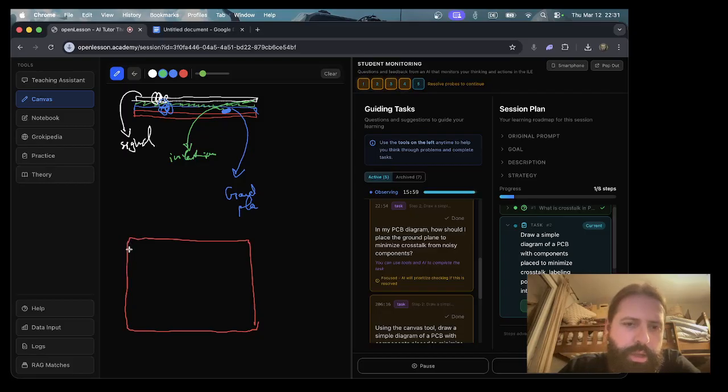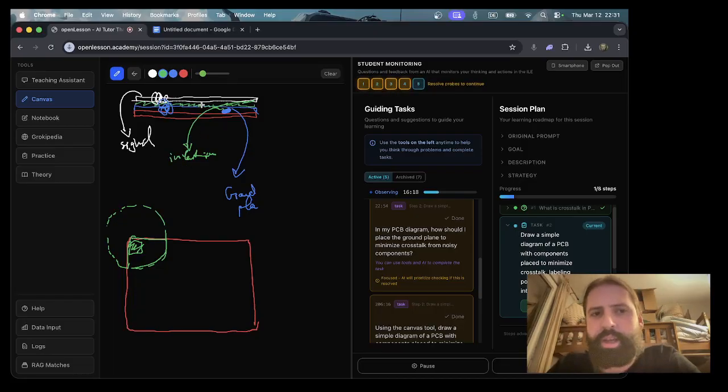Ideally, if I place power here and I am assuming there's a radius of noise, I'm minimizing the noise on the board to just this section. Then the microprocessor is going to be pretty noisy as well, my guess. It should be as far away as possible, so I would go in a diagonal.